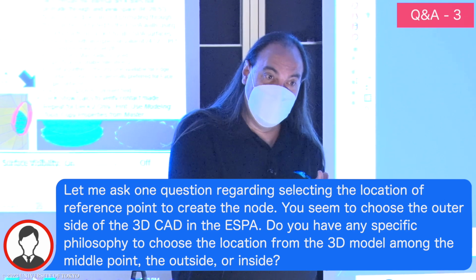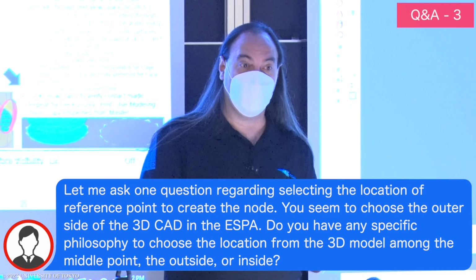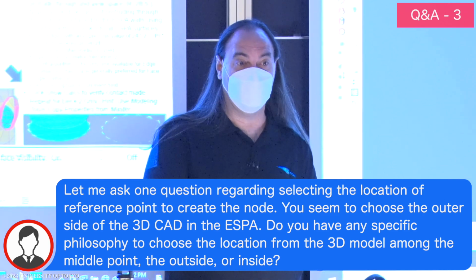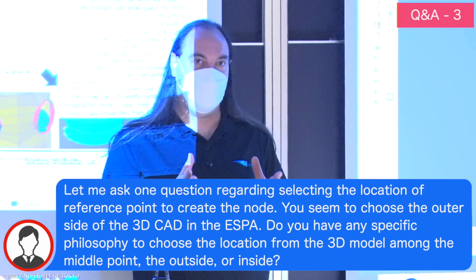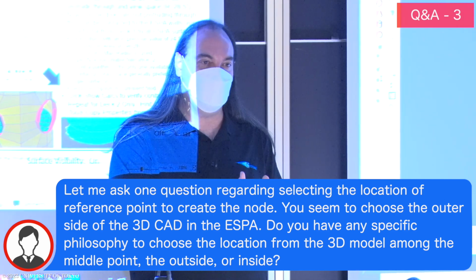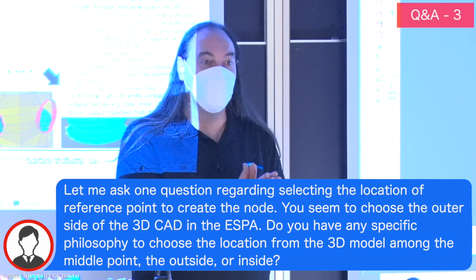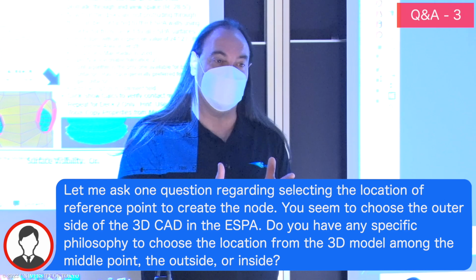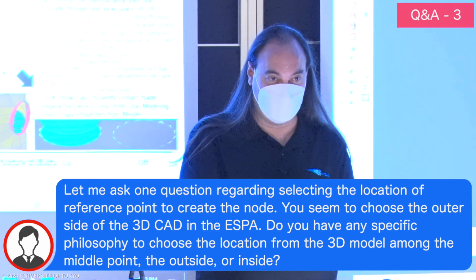If it's very thick, I might have to go with a solid at that point. I could choose either an FD solid or I could use solid elements for it. So you do have to make the decision as to whether you can abstract the thickness of your geometry to a two-dimensional surface and use the thickness properties, or whether you actually have to model it as three-dimensional with the gradient through the thickness. Does that answer the question?